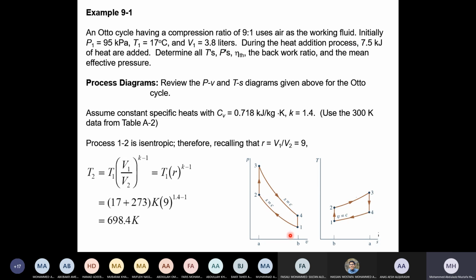What is given here, we have 4 processes. Therefore, if I want to plot this cycle here, I need P1 and T1 here. And all the time, P1 and T1, this is coming from atmosphere. This is at the inlet to the internal combustion engine, and this normally comes from atmosphere, and therefore this is normally atmospheric condition, 100 kilopascal, 300 Kelvin, or something like that.